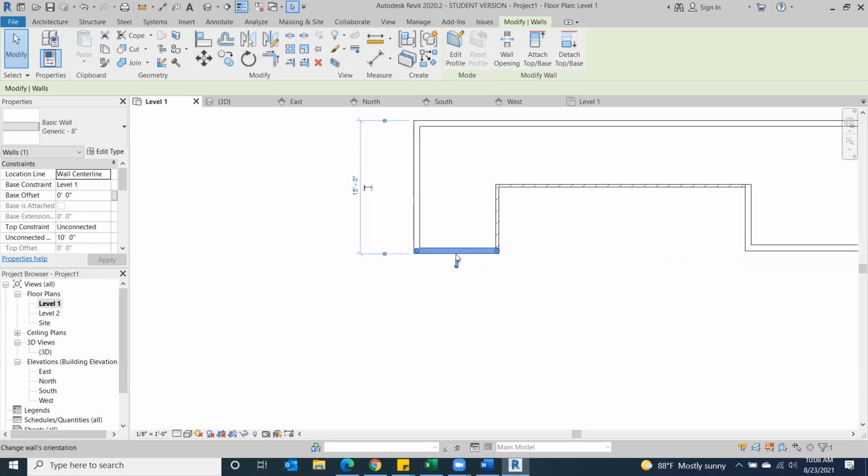So if I want this wall to stay right here in place at this measurement, 15 feet from this wall, I need to constrain it, much like I do in Inventor. We use constraints in Revit as well. They're not as thorough as that, and it depends on how comfortable you are using them and the practice that you're using.